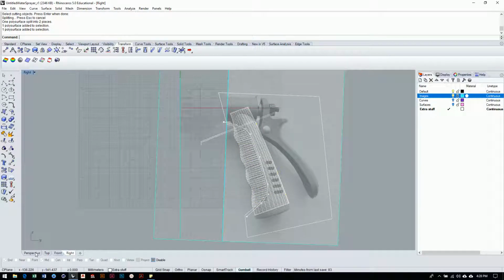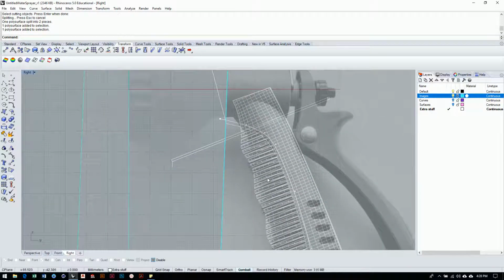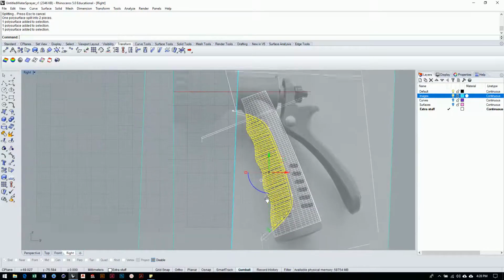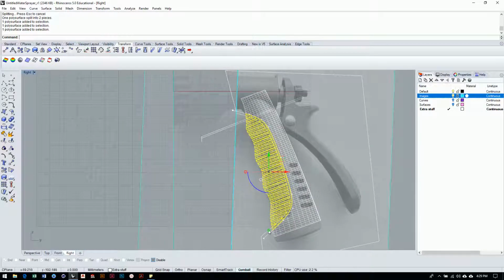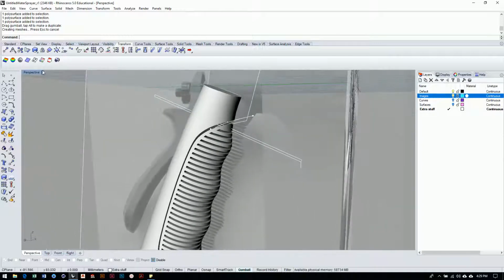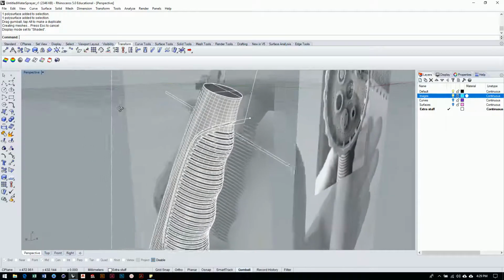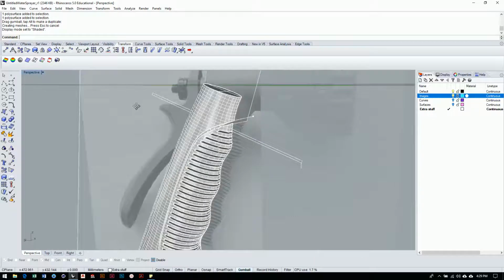And we'll go to perspective. Well, let's actually do it from here. It's a fun little trick. Take this section inside here, using the gumball. Just do a little, hold down shift and just scale it in just a little bit. Using the green box down here. Okay. And then go to perspective and look at the probably shaded view. Okay.